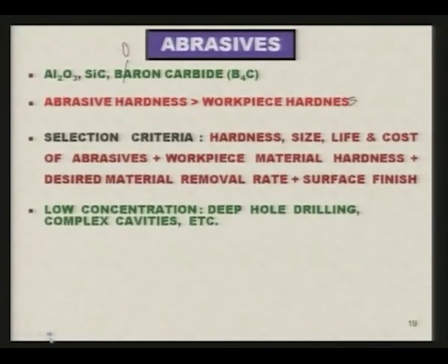Low concentration of abrasive is recommended for deep hole drilling, so that the abrasives and the liquid carrying the abrasive can penetrate inside, specifically in case of complex cavities.